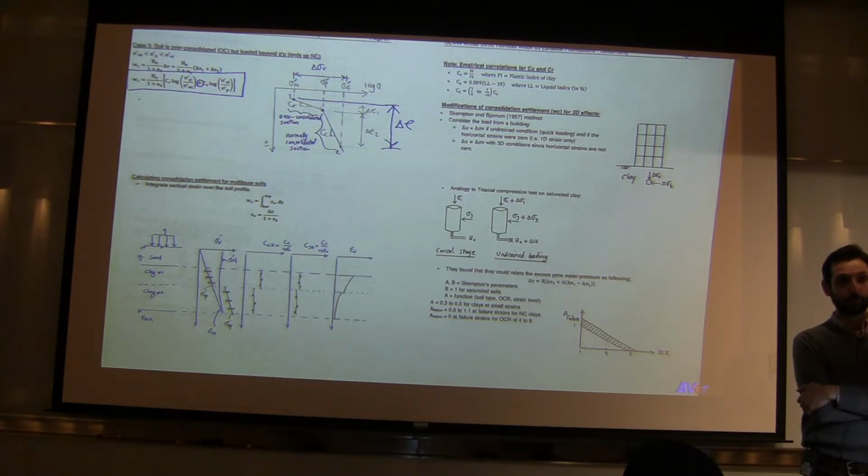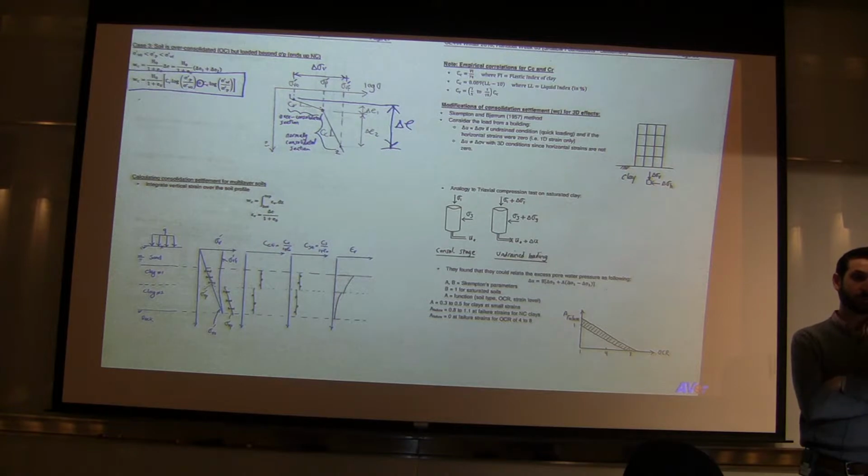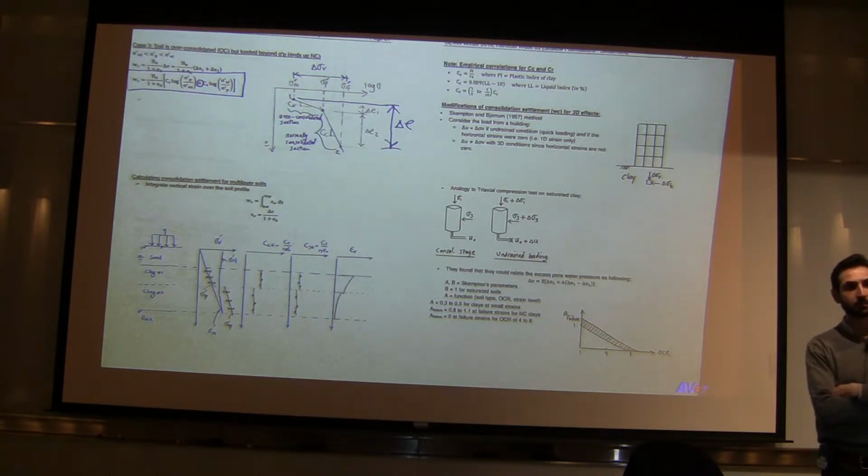And that's when you would rather do CPT than SPT, because in SPT you're bringing that soil up to the surface and you have to figure out what to do with that contaminated soil. In CPT you're just drilling the hole and you fill it up with cement or mortar and you leave it there. But yeah, that's roughly where the cost is.